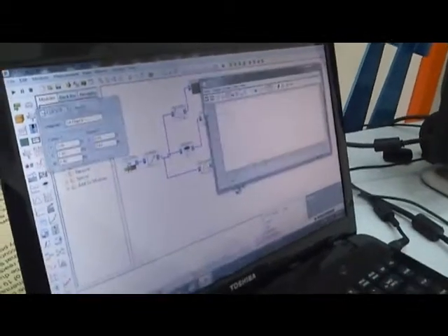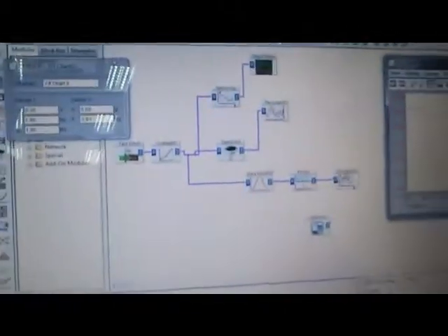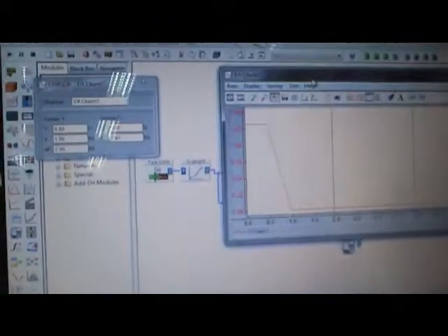This would be our layout for our natural frequency. We've already connected it to the data window, and we'll change it to rectangle with a block size of 2048. Then we'll connect it to our YT chart so we can have a display.